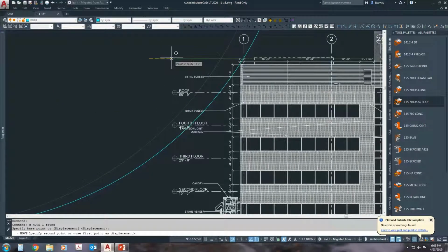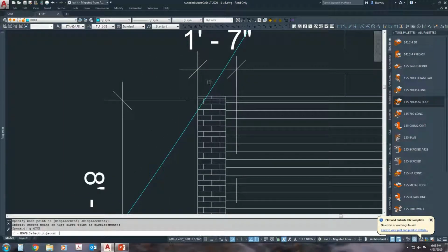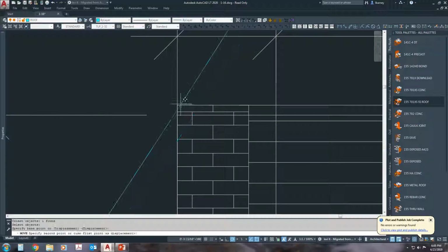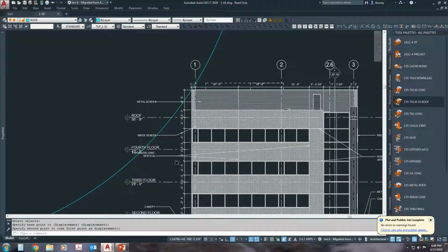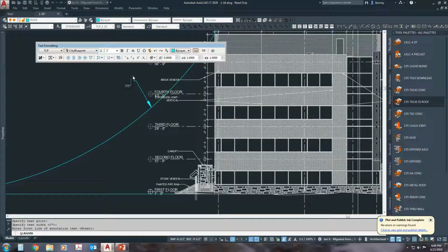As you can see, everything that's underneath this 150-foot arc is in the zone of protection. So that canopy down below is guaranteed not to be struck by lightning. So what I'll end up doing is taking this zone of protection and using it to figure out what needs lightning protection and what doesn't.